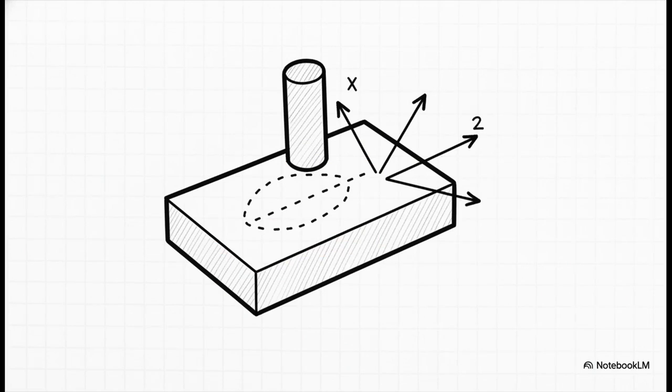But I want to leave you with a bit of a provocative thought here. Let's say you've manufactured a pin with absolutely perfect cylindricity and a block with absolutely perfect flatness. That's great, but how do you ensure that perfectly cylindrical pin is located in the exact right spot on that perfectly flat block, right? How do we relate these perfect shapes to each other to build a machine that actually functions? Well, that requires exactly what we completely ignored today. So the crucial point is we need datums.